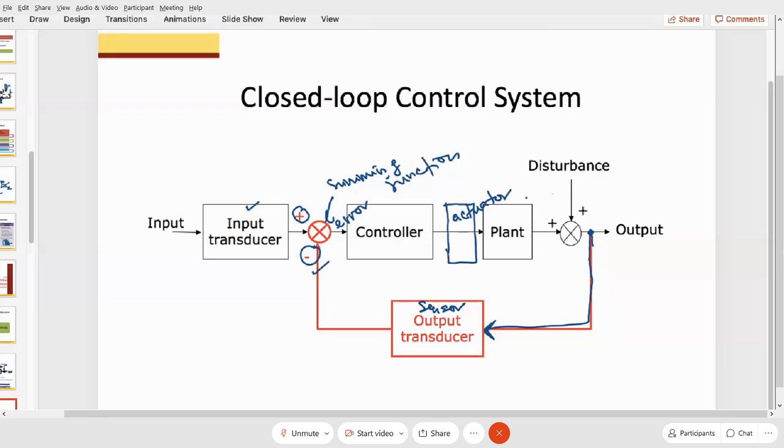Okay, so that is the closed loop system. Meaning that if you have a disturbance, for example many students and your room temperature reduces because you open the door or windows, the output will not be equal to the set point. Your system will measure the current status of your output and then compare it with your set point. So your compressor will react to the temperature difference. That is the closed loop control system.